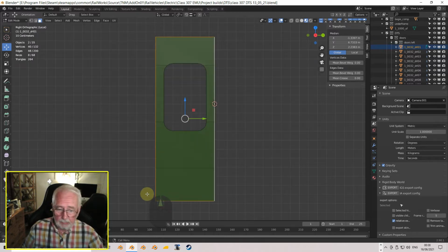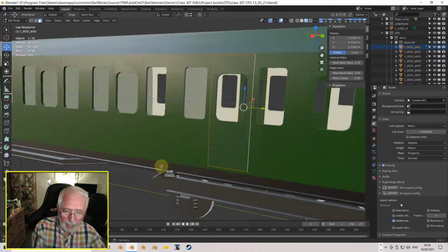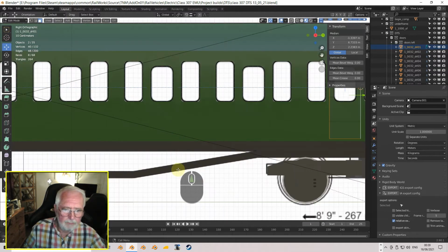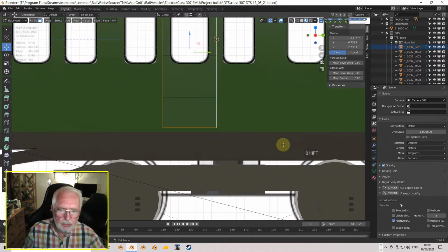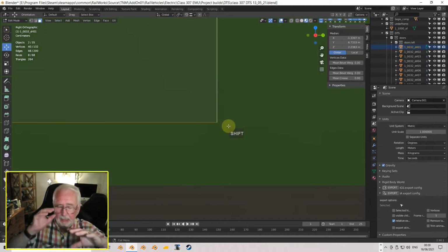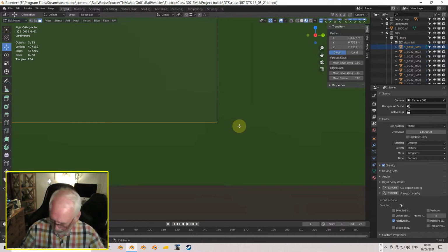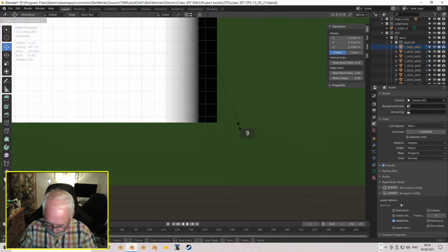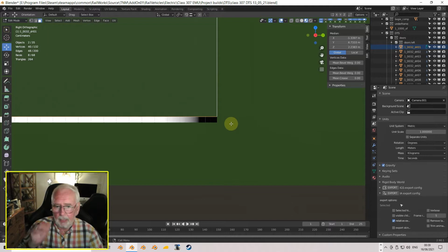Okay, go side view, bring back the vehicle. Okay, go side view and go to the corner there so you can see the scaling taking place. Okay, and then you can see whether it's right or not. Okay, so now I'm going to scale the vertical and the horizontal separately, because it doesn't tend to be uniform. So I'm going to scale Z, so scale Z 0.995. Okay, and now we've created a small gap there.